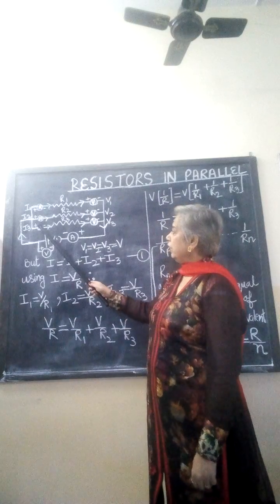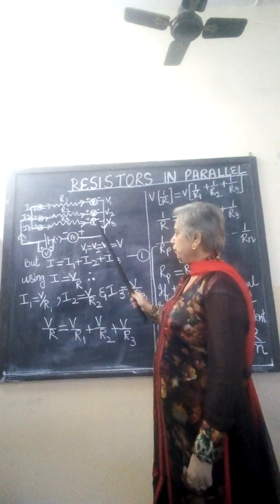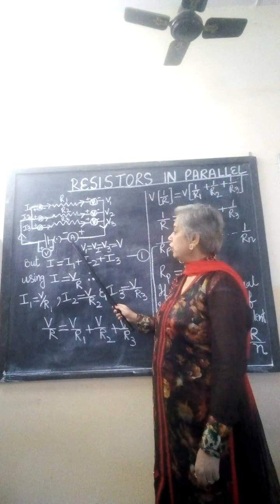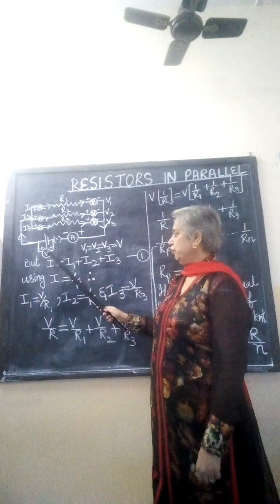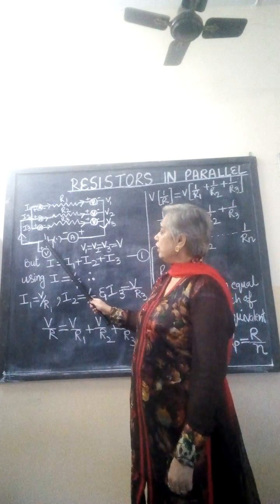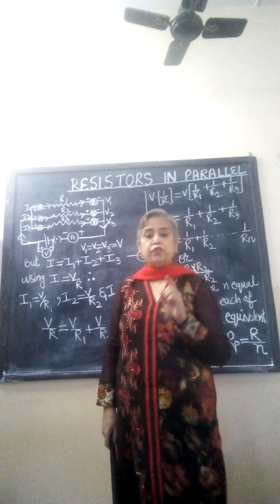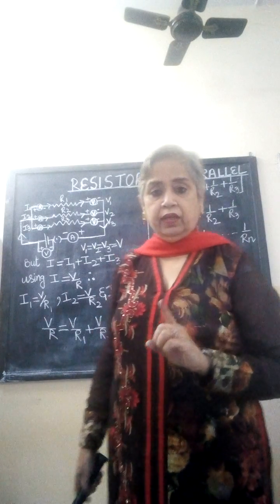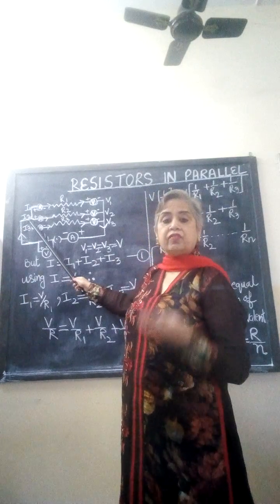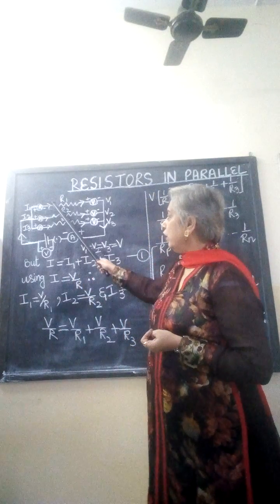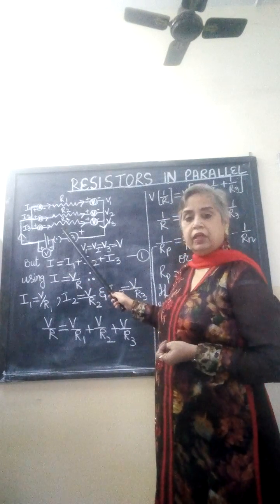Now you see I have connected 1, 2 and 3 ammeters across 3 resistors, and then there are 3 voltmeters. This is the ammeter to measure the total current, and this is the voltmeter to measure the potential difference. Right? Now you see when conventional direction of current is positive to negative, when the current starts flowing through this circuit, you can see that the current which is coming from here at this point gets divided into 3 components: I1, I2, I3. Each component going to the individual resistors.